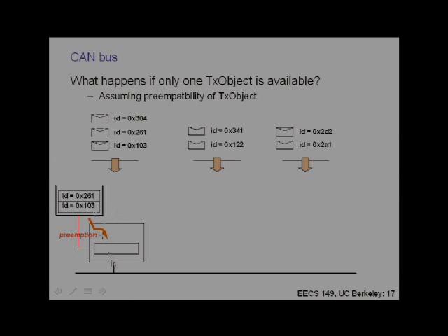If you had an ideal situation where you had infinite buffer space, this wouldn't have happened because when both of these arrived, they would have arrived at the same time. And if you had no preemption delay, then 103 would have been put on the bus at the same time as 122. This would have backed off, and 103 would have been transmitted, right? Because you had a finite buffer space and finite preemption time, you had an inversion. Okay.